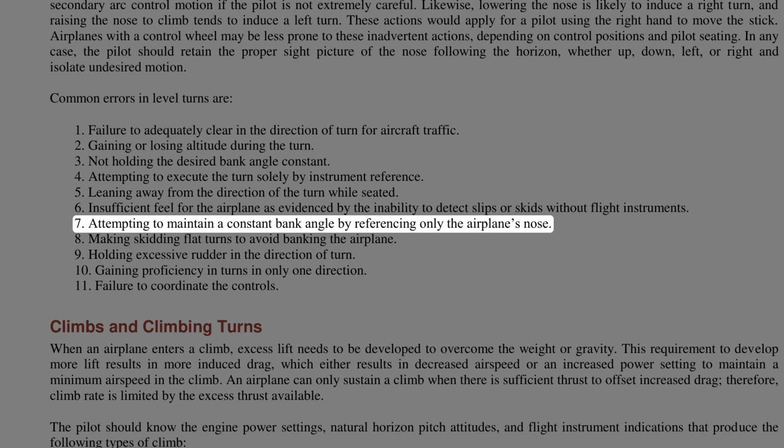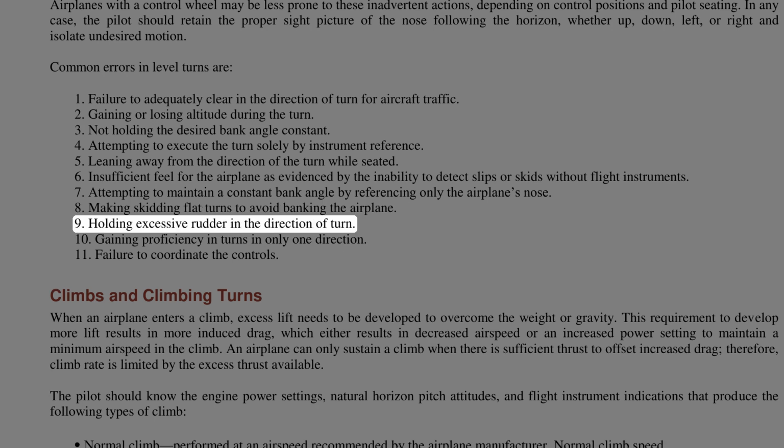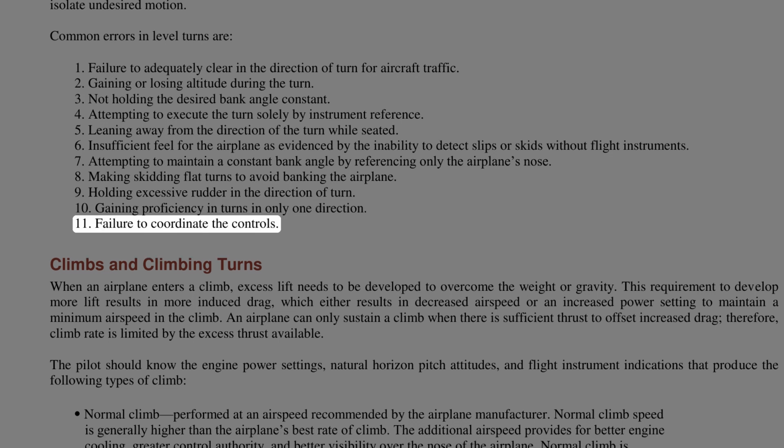7. Attempting to maintain a constant bank angle by referencing only the airplane's nose. 8. Making skidding flat turns to avoid banking the airplane. 9. Holding excessive rudder in the direction of turn. 10. Gaining proficiency in turns in only one direction. 11. Failure to coordinate the controls.